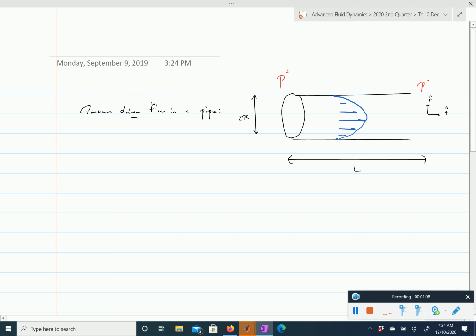So how do you get there? What are our governing equations? So we've simplified the governing equations for a laminar viscous flow which is unidirectional. So first, in this coordinate system, we have our z-axis in this direction. So the flow is along the z-axis. We only have flow in the z direction, and we don't have flow in the circumferential direction, and we don't have flow in the radial direction. Okay, flow velocity. So the continuity equation simplifies to partial u_z partial z equals 0.